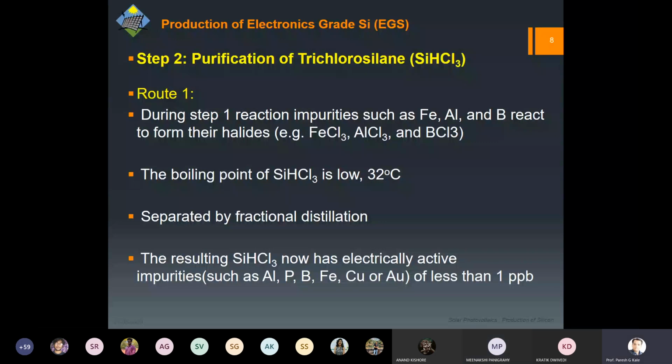No. See, that's why this is not a technical question. This is a common sense question, because you initially remove whatever impurities are there, right? Try to purify it as much as possible, and then when you want to dope it, we require very fine control of the material. That's why you cannot say that P and B are there, let it be there, then we will count it. Later you cannot count, right? And you cannot adjust it, right? So better to purify as much as possible, and then when you dope it, we have that precise control. So that's why right now we will not worry about even some good impurities going out of this. Okay.